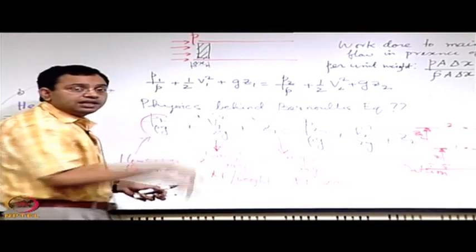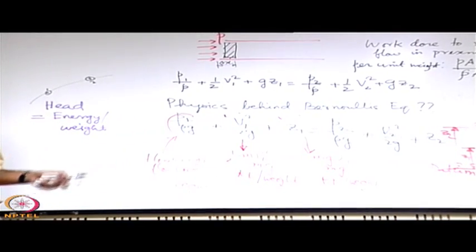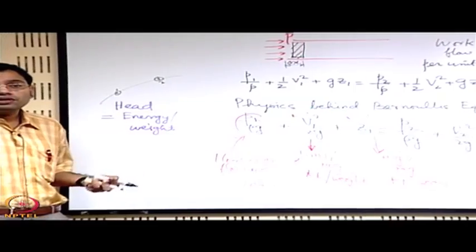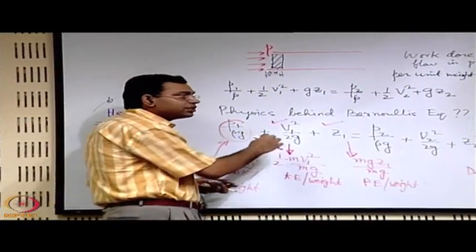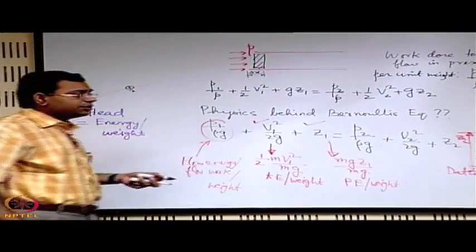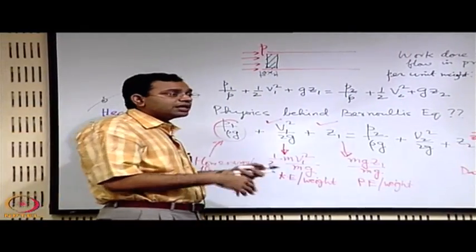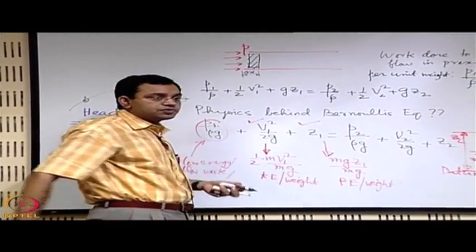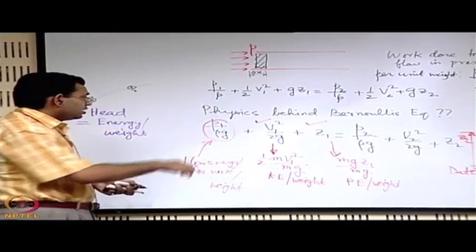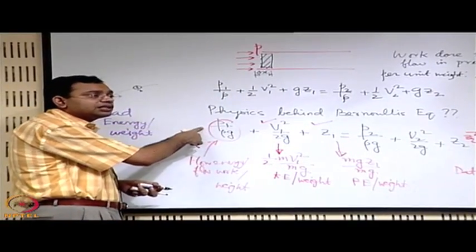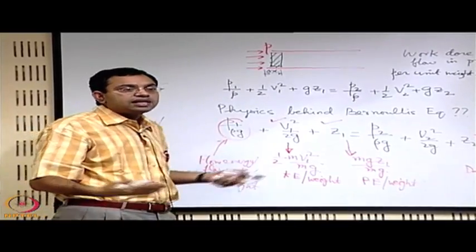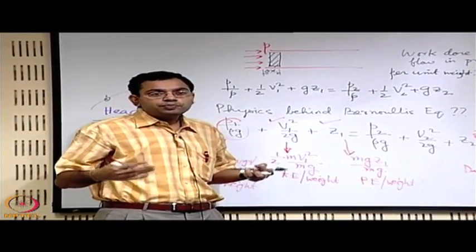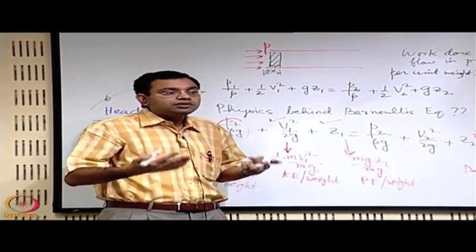For the kinetic energy term, there is a velocity and you require a reference for that. So, there should be a reference frame with respect to which you are prescribing this velocity. Typically this reference frame is a reference frame at rest. So, you are writing here the absolute velocity, and this reference frame for pressure is also very important. We have already discussed when we were discussing the statics of fluids that you can prescribe pressure also with reference to something.